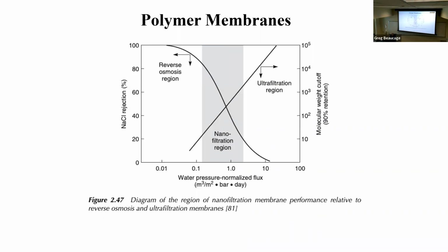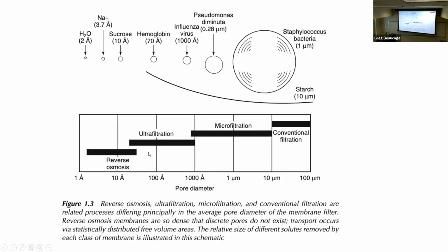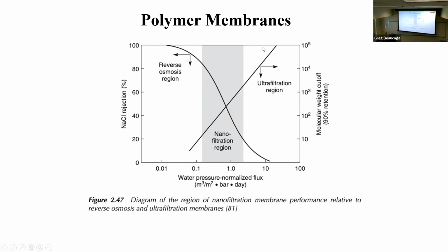So this is a map that shows, say you're doing salt, removing salt from salt water. And this is a thing that's kind of hard to understand, this x-axis, but basically pressure goes up. So if the pressure differential goes up, then you get to reverse osmosis, where you're driving the fluid through the membrane. And the pressure goes down, and you get to filtration, like this kind of ultrafiltration thing. Microfiltration, ultrafiltration, and finally you get to osmosis. Like the pore size is changing here too.